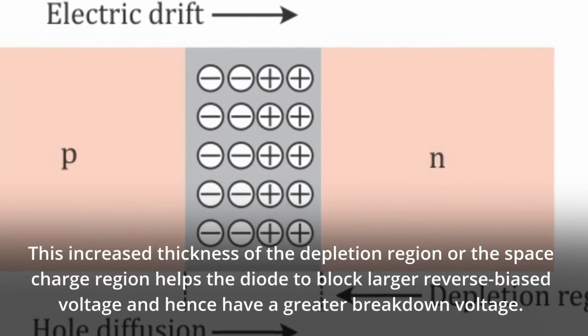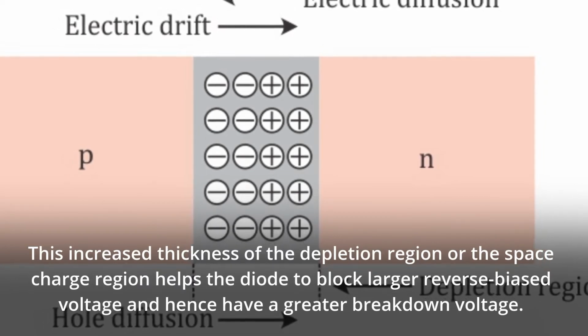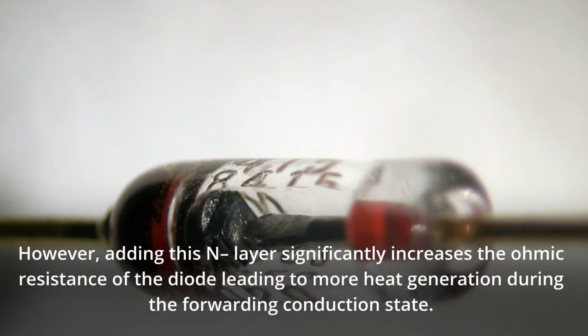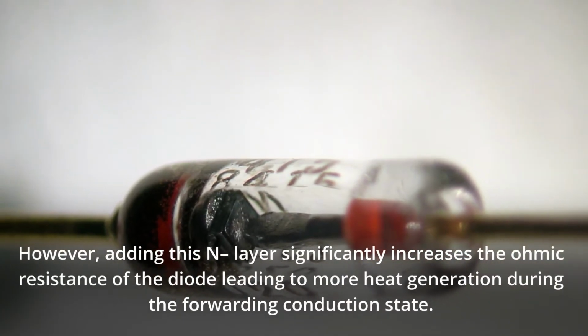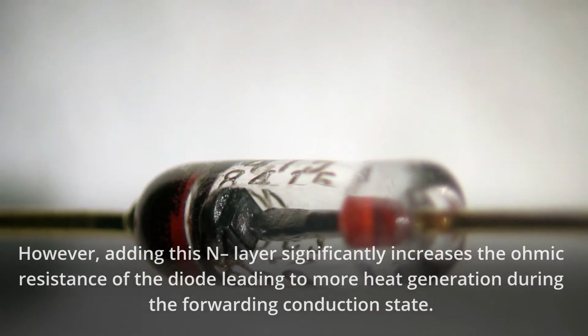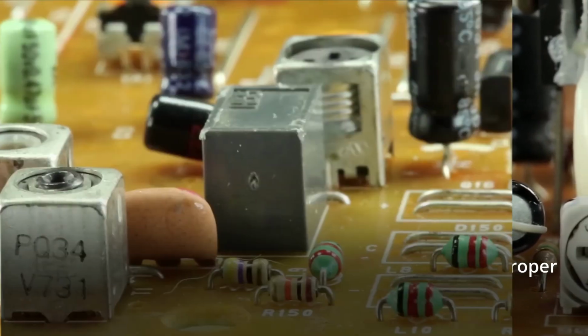This increased thickness of the depletion region or the space charge region helps the diode to block larger reverse biased voltage and hence have a greater breakdown voltage. However, adding this N- layer significantly increases the ohmic resistance of the diode, leading to more heat generation during the forward conduction state. Hence power diodes come with various mountings for proper heat dissipation.